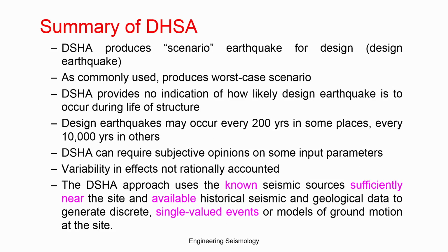The design earthquake may occur every 200 years, in some places every 10,000 years, and in others, as we have seen, some places have frequently occurring earthquakes, which are plate boundary regions. In some places it occurs once in a while, in the interior of the plate or mid plate. So, considering the worst scenario for that kind of interval will be too much of an investment. Okay. So, DSHA can require subjective opinion on some input parameters, and variability effects are not rationally accounted for.